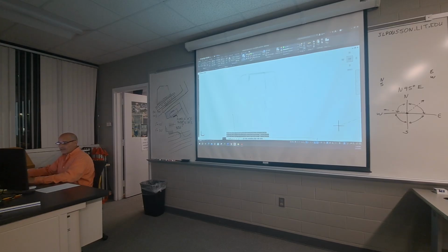Next side, at my distance, 350.31 feet is less than my angle, south 81 degrees, 43 minutes, 42 seconds west, and then C to close. And then I'm gonna double click my mouse wheel and see what I got.